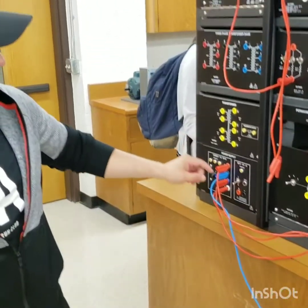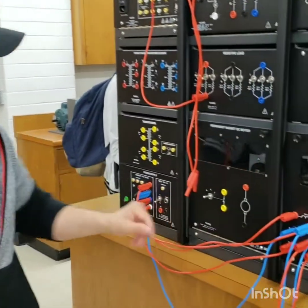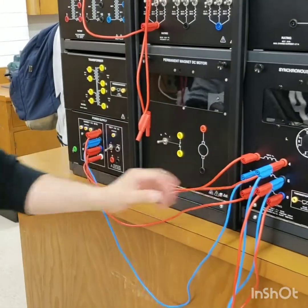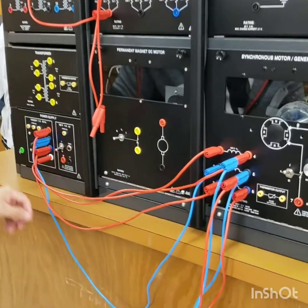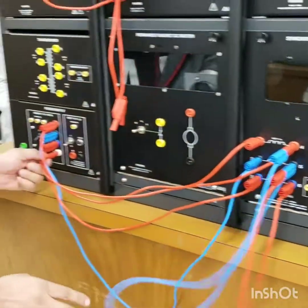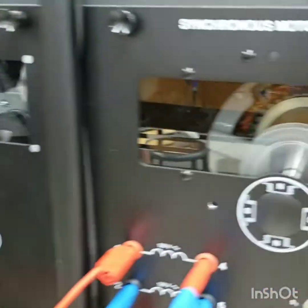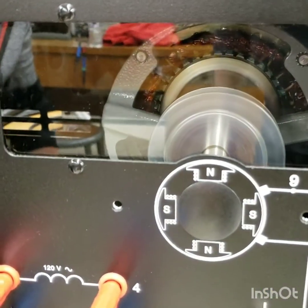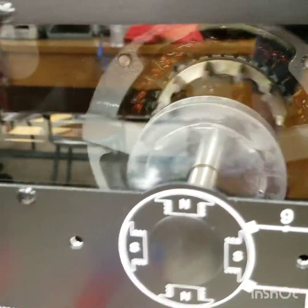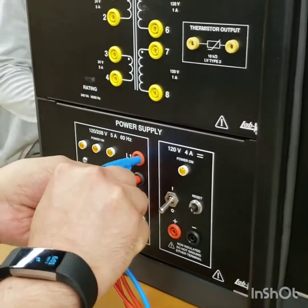So we're going to go ahead and connect our power supply to our generator by connecting lead 1 to port 1, lead 2 to 2, 3 to 3, and then we're going to connect 4, 5, and 6, and it was a Y connector, and run it down to our neutral, and we're going to power it on. And we can see it's running clockwise. But if we switch L1 and 2, we should see that it runs counterclockwise.